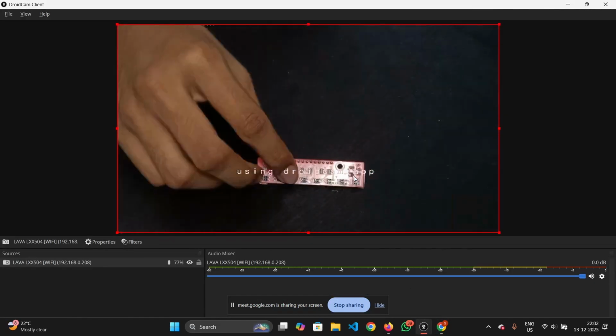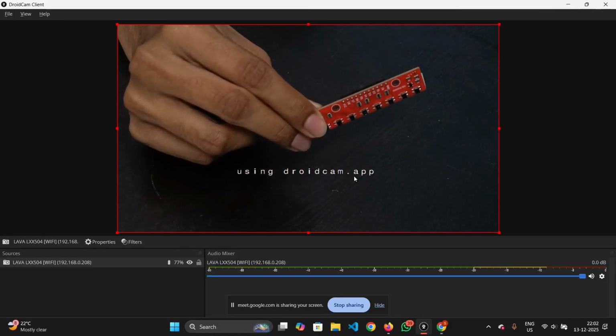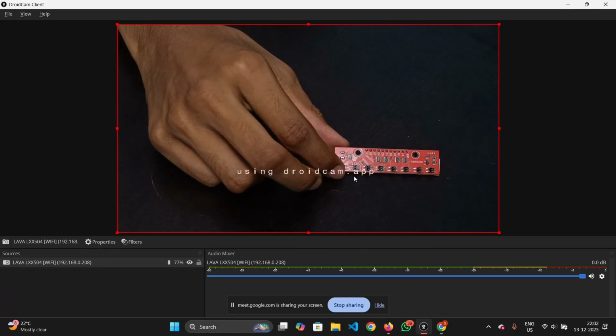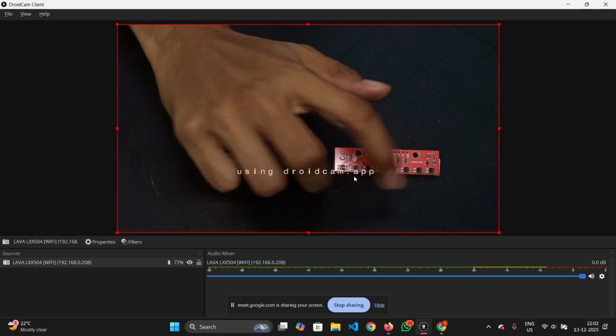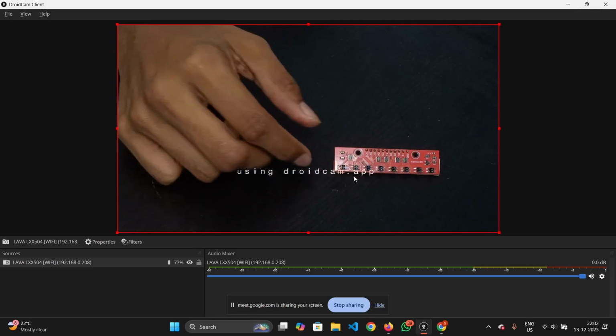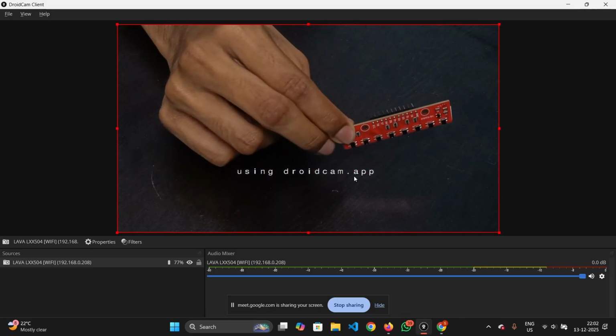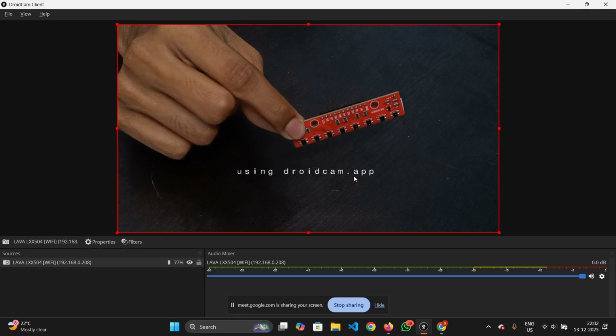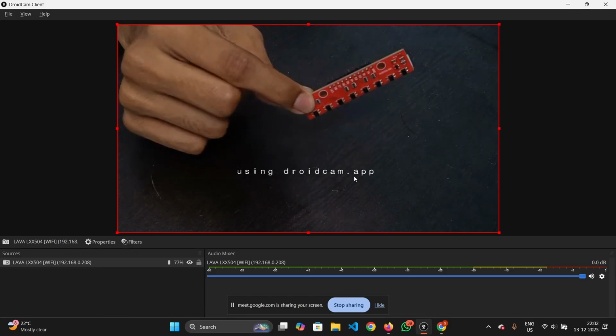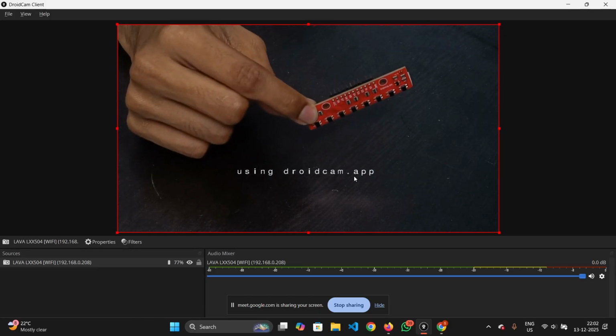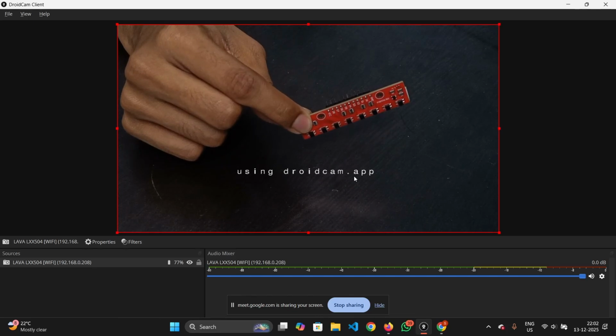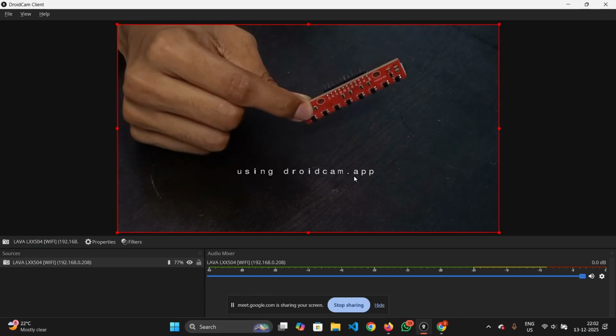So, during our iBots event, we use this thing. This is an IR sensor array, and basically it has 7 IR sensors. It gives you more accuracy or control. It tells you more precisely where the black tape is, so you can control your line follower robot a bit more precisely.